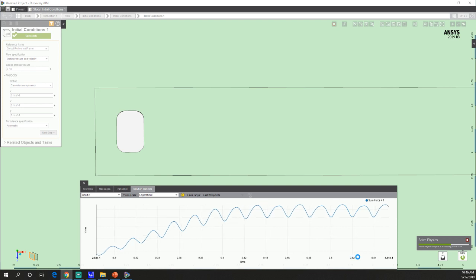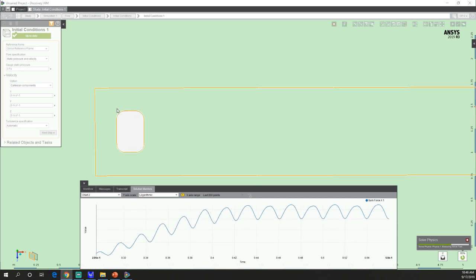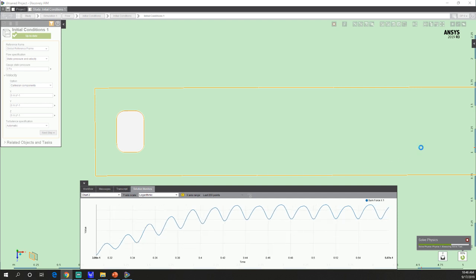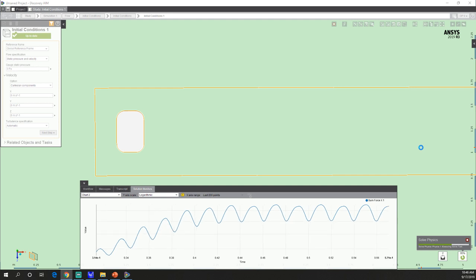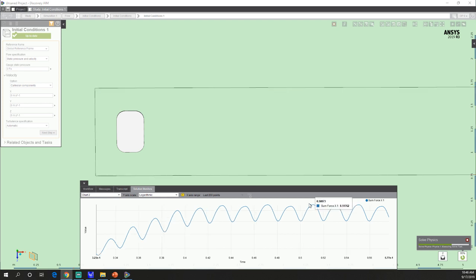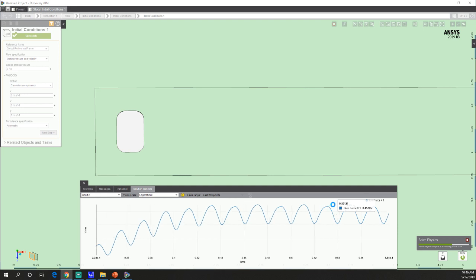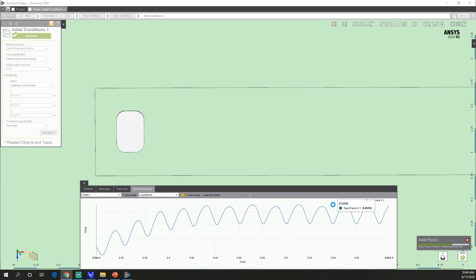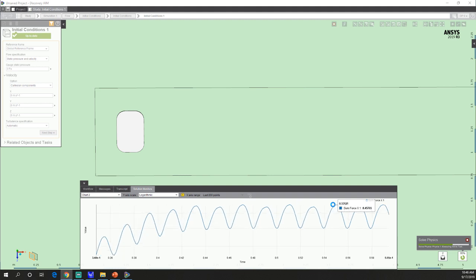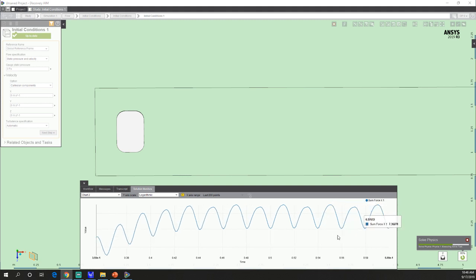Years ago, I was at a CFD conference, and one of the speakers said, "Hey, if you have a model like this and your tool can only predict kind of steady state behavior, that's not really useful." And we see that here because in steady state, we predicted a drag of like 3 newtons. But in reality, with transient, it's much higher, right? It's 8, but it's still better than our square-shaped antenna, which was at 11. So this is a 20-30% drop from that, but it's certainly not a 3 Newton force like we were hoping with a steady state simulation.